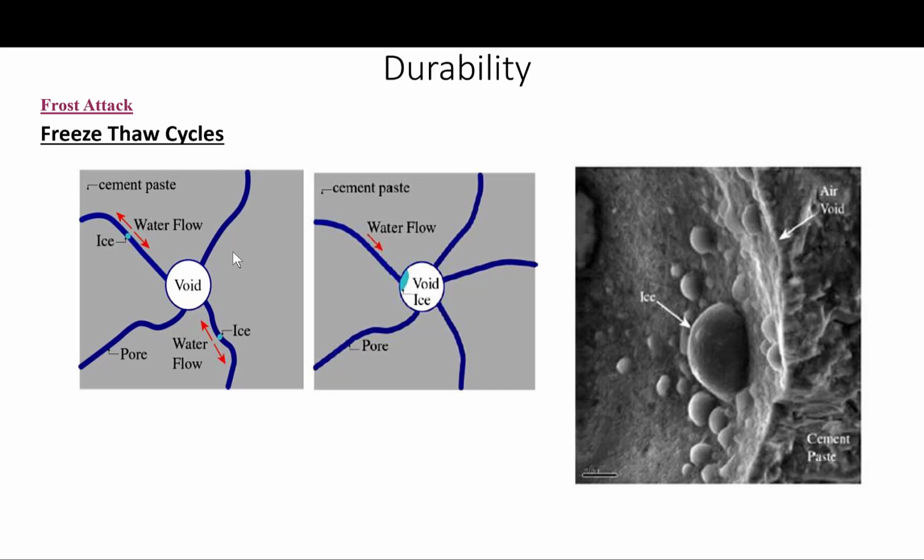Upon thawing, the water in the air bubbles returns to the cement paste because of the higher surface tension in the smaller capillary pores. In this way, cement paste will not suffer freeze-thaw damage as long as the moisture content remains constant. That's something else to remember. Even poorly air-entrained concrete will eventually be damaged if it becomes fully saturated with the air bubbles filled with water. So that's another factor. The moisture plays a role here that we have to be aware of.